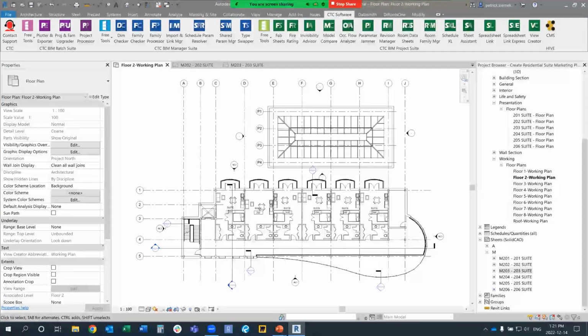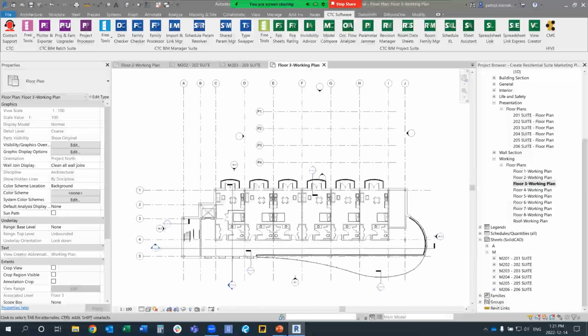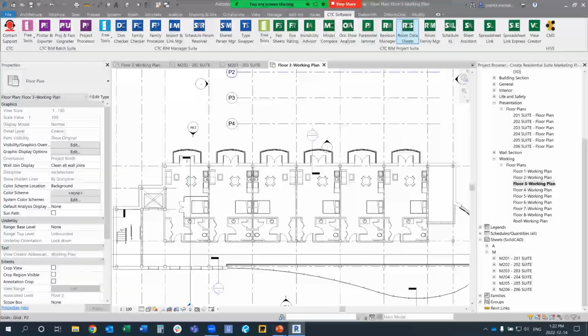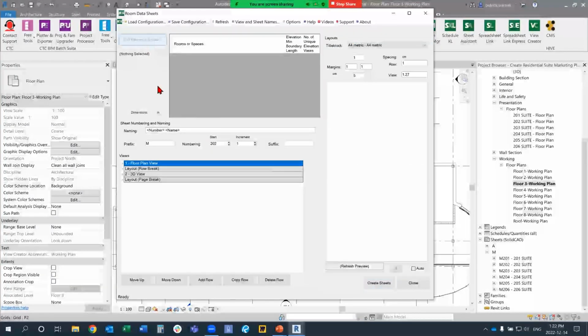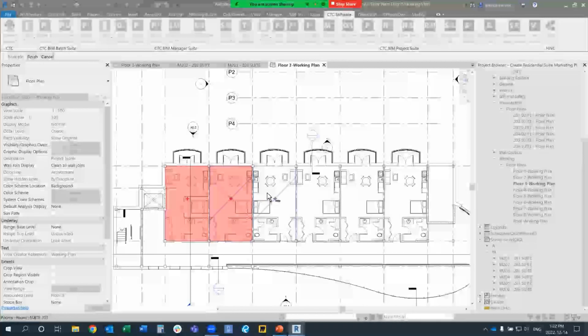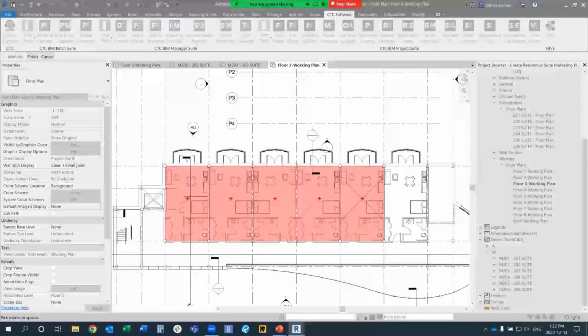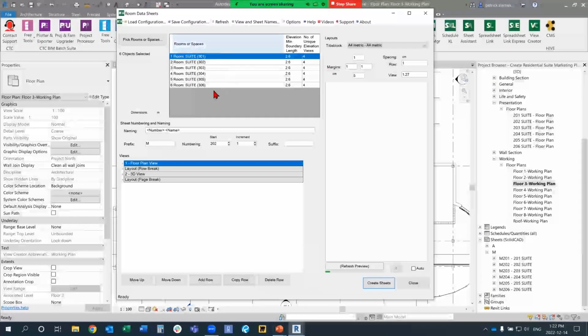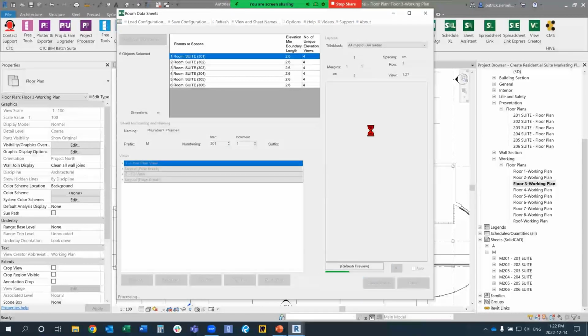To quickly show how we continue doing that, I can go to another view itself without room tags added to it. Since I already know it starts from 301 to 306, I could come into here, start selecting the rooms, finish those as needed, have them already in order, just start changing the numbering, and refresh the layout of the page.